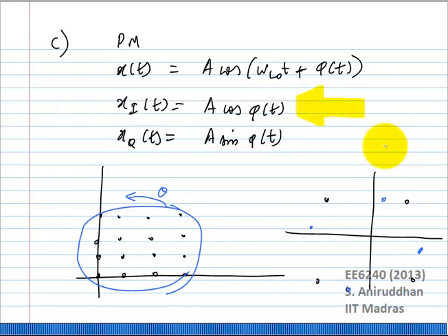Okay. Now, as it so happens, if you have any kind of frequency error, you will end up mixing up these subcarriers badly. You really cannot afford to have a lot of frequency error, and normally the frequency error specifications are very, very strict. You will see errors of the order of 0.1 parts per million.